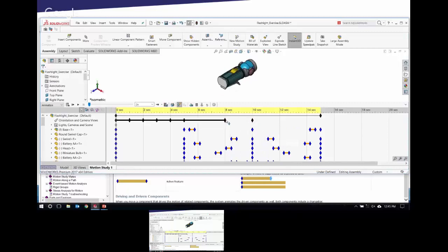So this is now the identical orientation between these two keys. That's why there's no change bar, there's no black bar between them. And then let's say I want to go back to this position at the end of the animation. So I'll right click and copy this, and I'll right click and paste it here. So now it is interpolating between those two.